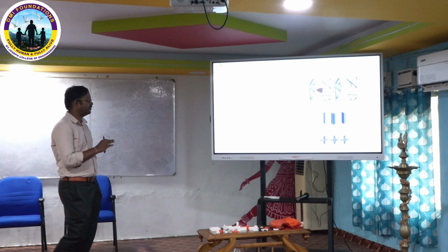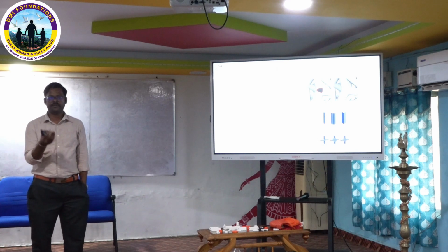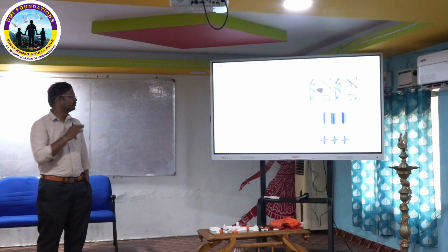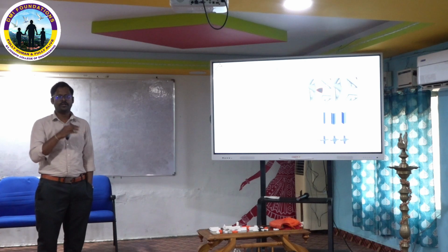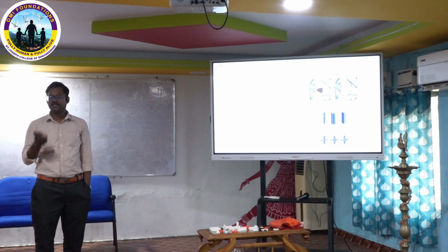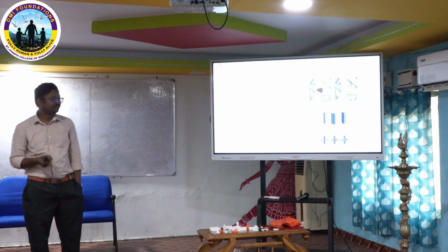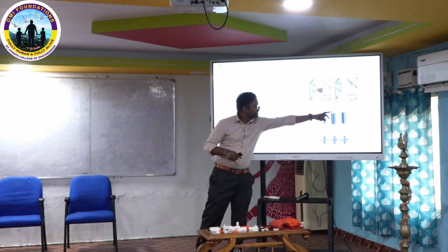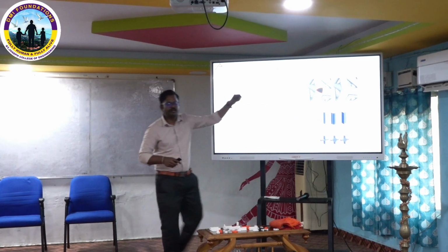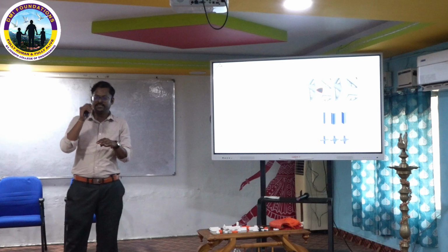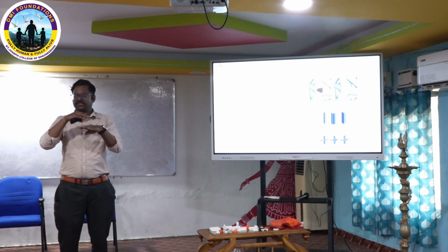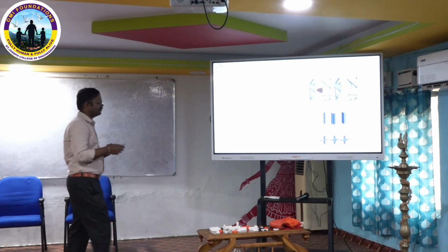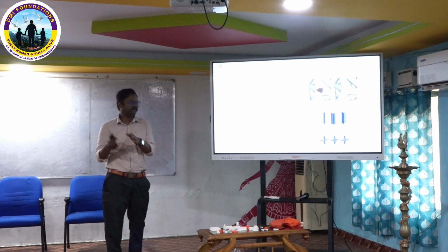The next one is meshing difficulties. Obviously we are going with structures of 1 mm or a maximum of 2 mm diameter, and that too a more complex structure. So meshing is more difficult. You have to sit for that and do one month of meshing, and only then can you get proper meshing for your lattice structure. Then the third one is contact and boundary condition challenges. Because I have this kind of cross section, when I give the contact area I have to select each and every top surface of the stud, then merge that with the compression plate. That takes more concentrated work.